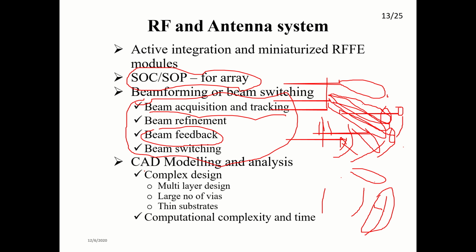So why is it a challenge as well as a source of a lot of opportunity? Because it's a highly complex design. I think we have discussed enough on that. Multi-layer design, a large number of vias, because you will have plenty of vias. You cannot just put vias like that, because every via will have an impact on every other component.